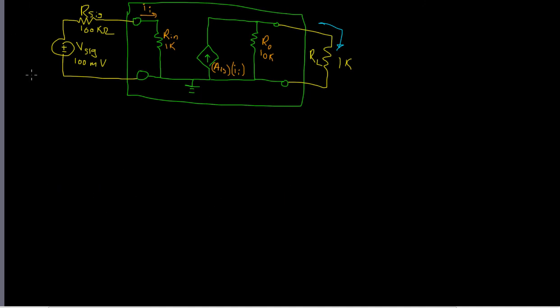And so the voltage gain, defined as VO over Vin, is going to be similar. First of all, we can rewrite VO as IO times RL, because it's this voltage here. This is VO. It's the voltage we measure at the output, so it's only going to be across this RL resistor. So that's just Ohm's law, replacing VO with IO-RL. And that's still over VI.